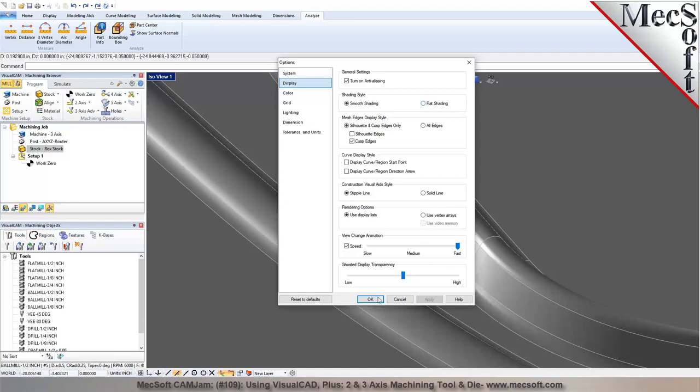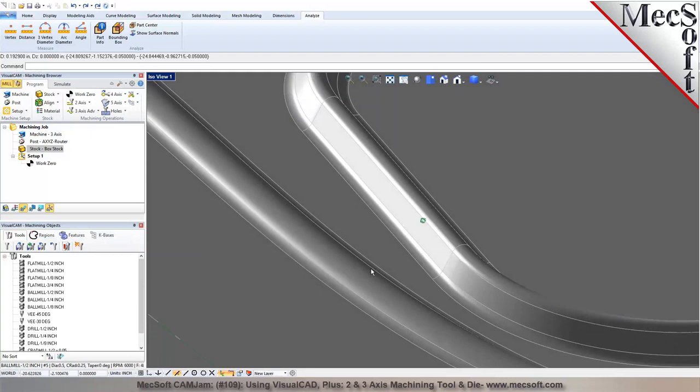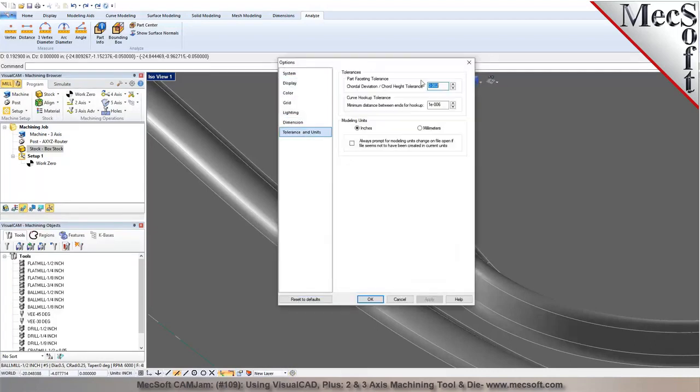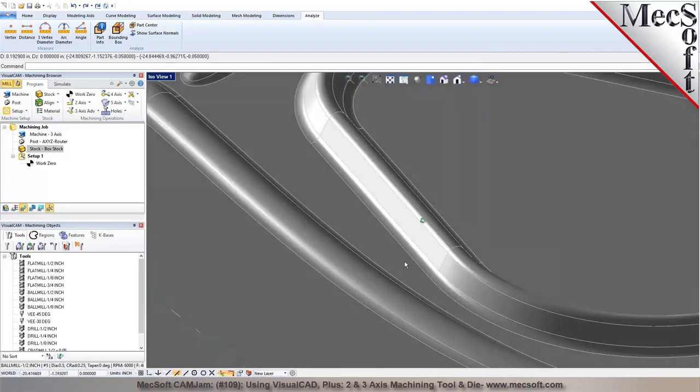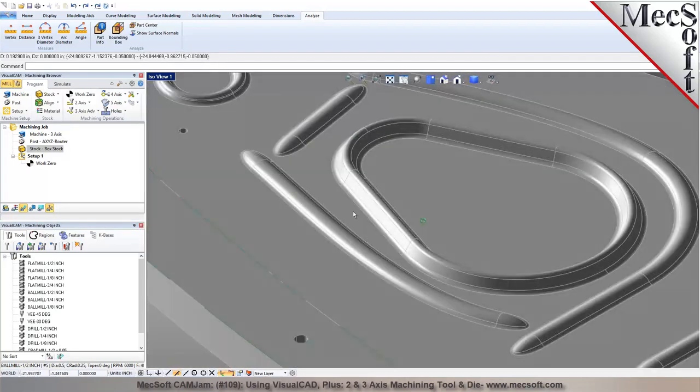Okay. And that's really just what you display right there. Well, this will be what you see when you machine it, actually. So you want to go back and import it with a much tighter tolerance. Okay, very good. So I can change this back from a 2 thou to a 1/10,000th of a tolerance, and then I can bring it in. So it'll reduce those facets, make them much smaller. Okay. All right.